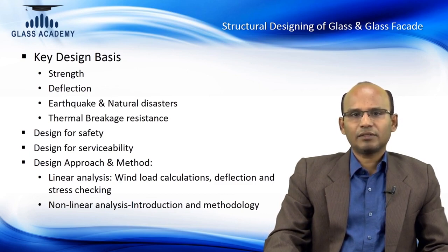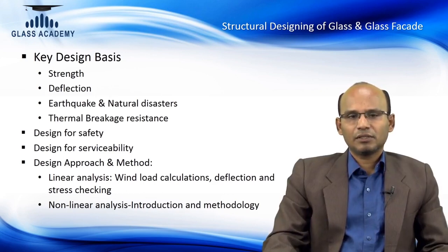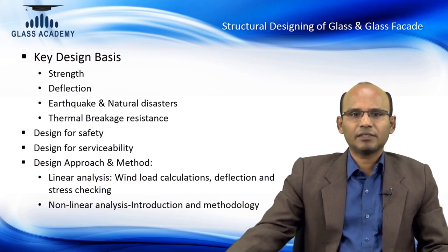the factors are wind load factor, dead load factor, live load factor. Different factors are considered with suitable combinations, and in some instances the design needs to be checked for non-linear behavior. Non-linear is critical if you are doing slender elements, small size glass fins, used for large spaces. If the slenderness ratio is too small, then the slenderness factor is critical.